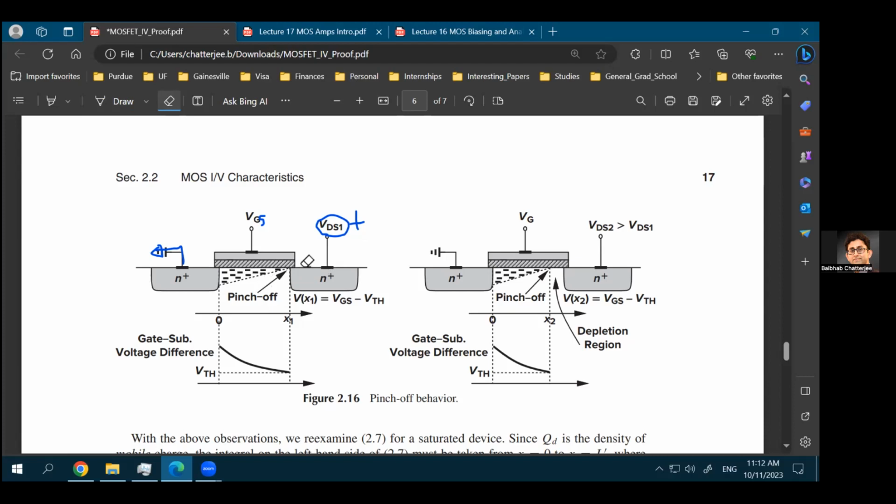What will happen in this case is that as the depletion region is becoming wider, as you are applying more and more drain to source voltage, you'll see something happening like this. Your channel, instead of looking like a rectangle, so let's say your channel looks like a rectangle initially, with all these negatively charged electrons through the channel. What is now happening is that as you are creating this depletion region around your drain, some of these electrons are not present anymore in the channel. The channel almost looks like a triangle instead of a rectangle, right? Initially it will look like a trapezoid, then it will look like a triangle, then it will start looking like a smaller triangle as you start applying more and more drain to source voltage.